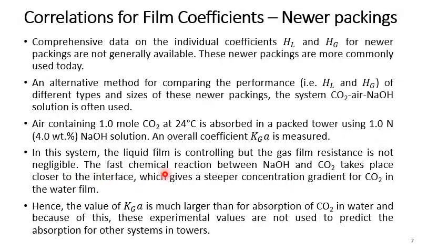So you need to measure the concentration gradient for CO2 in the water film, actually in the liquid film, and also in the gas film. Okay, but in this case, the value of kGa is much larger than for absorption of CO2 in water, and because of this, these experimental values are not used to predict the absorption for other systems in the towers, because this is actually a reactive absorption.